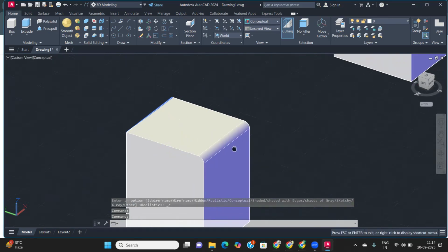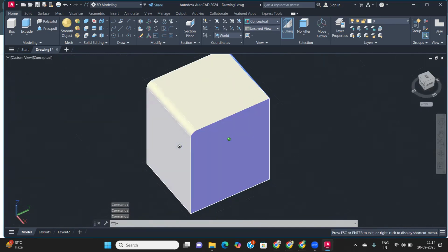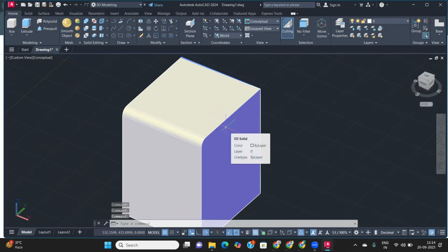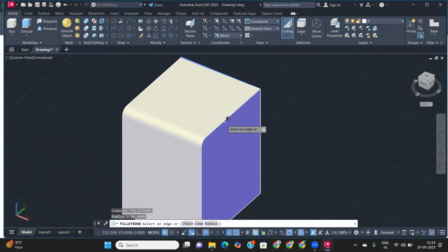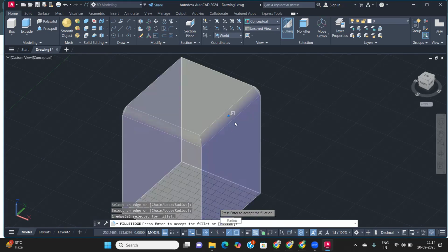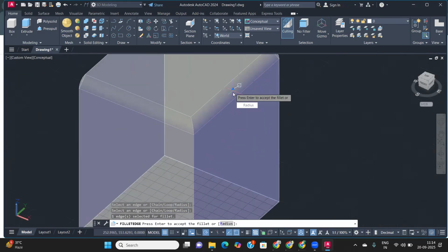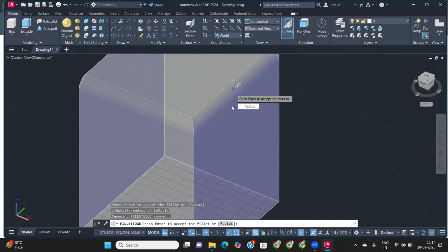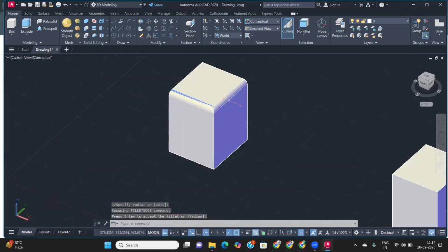Okay, and then if you want to do it the manual way, how can we do that? I want to fillet this part. Just select the fillet edge, right? And then select this edge first. Click on this edge, and then hit enter. Then here we have one option. This is your option. You can click to increase and decrease the edge radius by using the manual way. And then we hit enter, then you can create the edge, right?